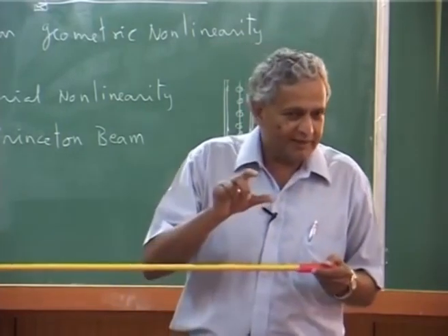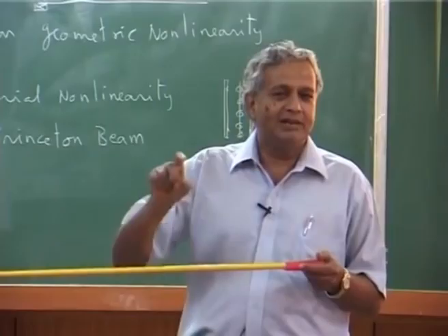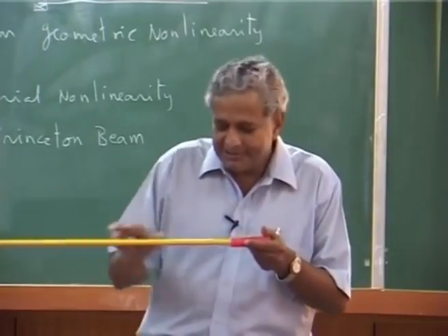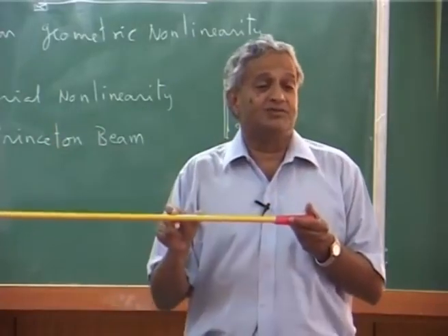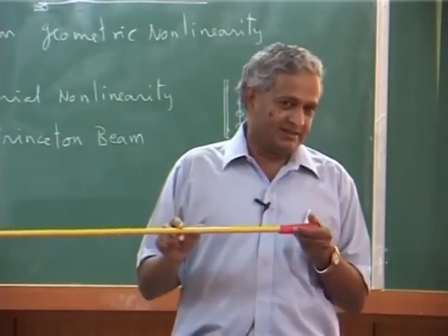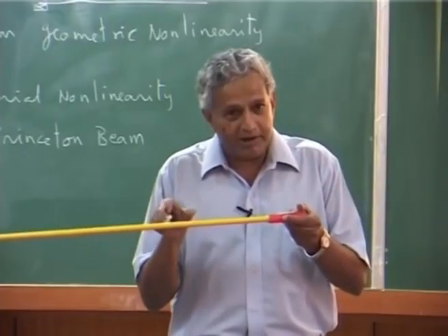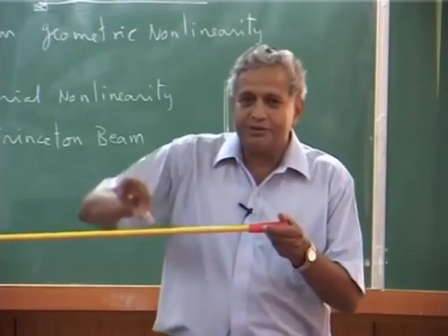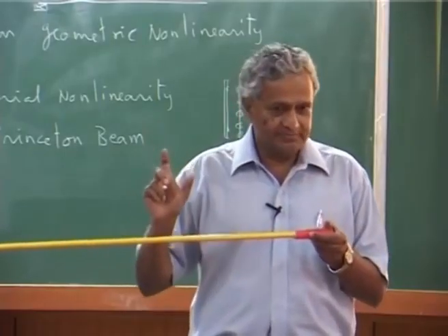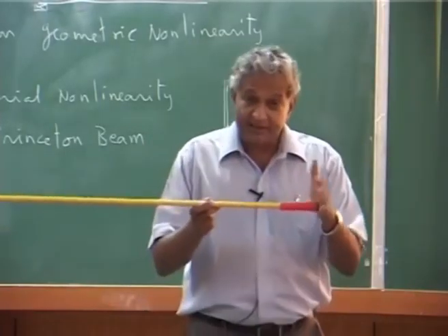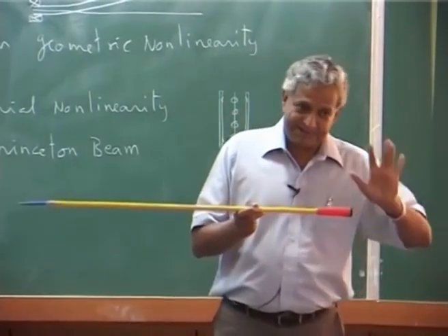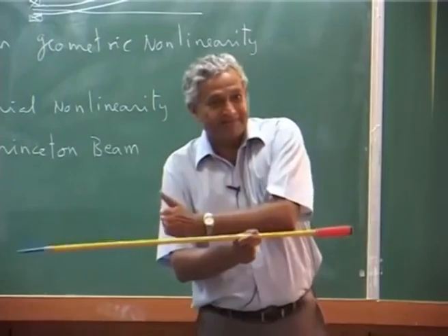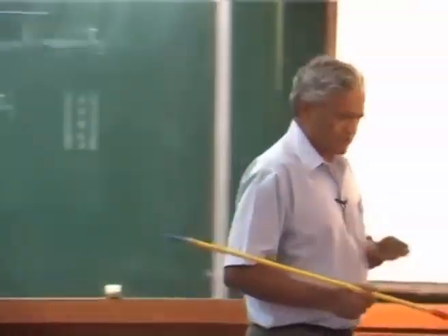There is no flap hinge per se, but there is an equivalent flap hinge, where some soft stiffness drops at some section and that becomes kind of a hinge. It is a virtual hinge. It is not a physical hinge, but some point is soft, therefore, it can flex about that point. But the pitch bearing is inboard. Most of the hingeless blades have the pitch bearing inboard, you do not keep it outside. But you see that goes into construction.